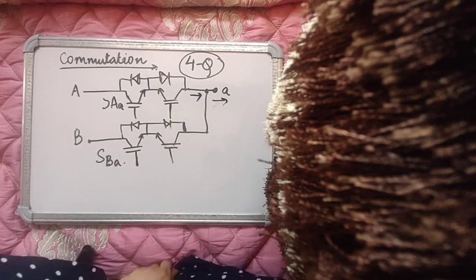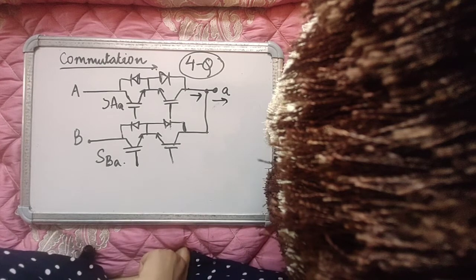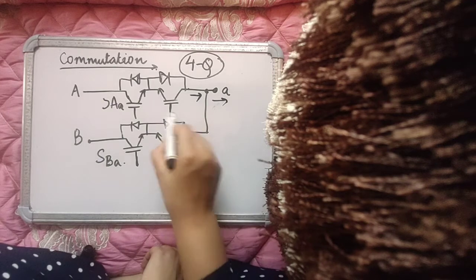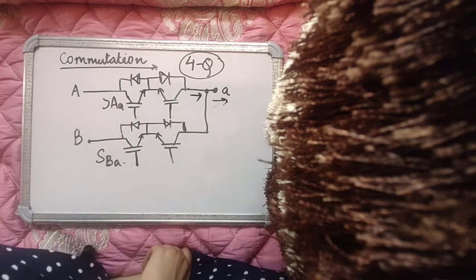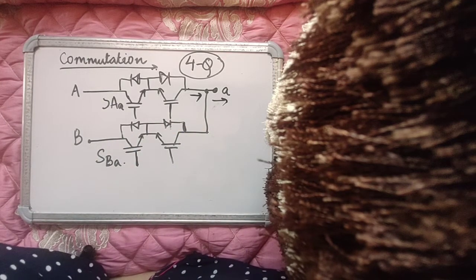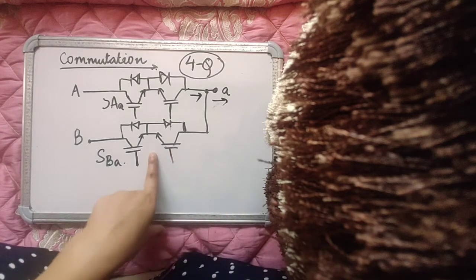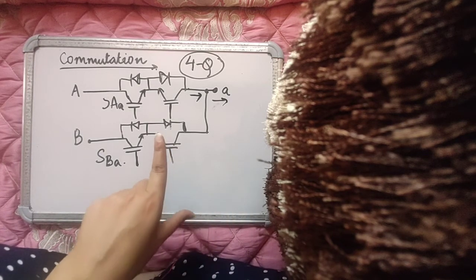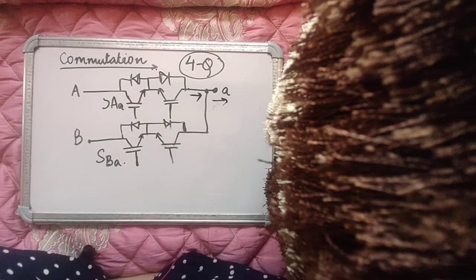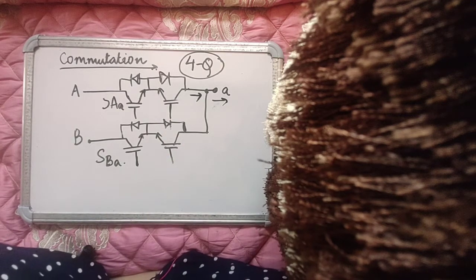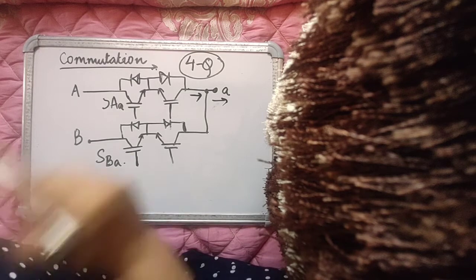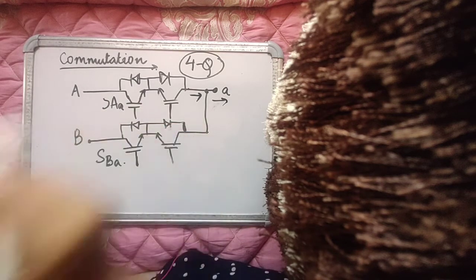And in the future also, it is expected for various applications like electric vehicles, especially electric vehicles, you are going to use these as the bidirectional switch cells, if not as a matrix converter topology, even in DC to DC topologies or AC to DC topologies, it is possible to use this switch cell because of the advantages that it offers. But whenever you have to deal with such switch cell, you have to take care of the commutation. So how do you basically commutate such devices? How do you transfer current from this switch to this switch?